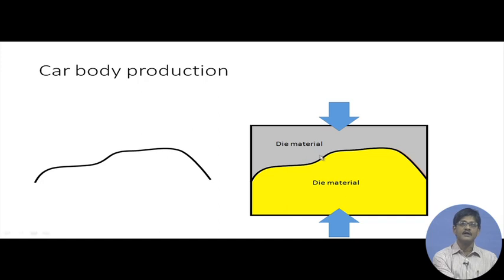If we plan to make these dies with the help of 3-dimensional machining, it is no doubt possible, but it will require a lot of expenditure because of tools. Tooling expenditure will be high, because we have to cut strong, tough materials. Tool wear will be high, and therefore, expenditure for tooling will be quite high.